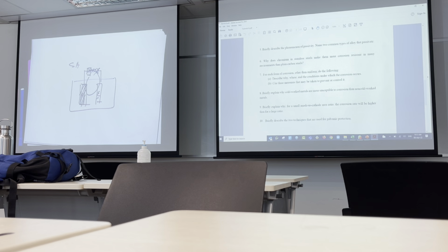Okay, so the two methods: sacrificial anode and impressed current. With impressed current, you do not have a consumable anode that has to be replaced. You use something that's inert. Inert means it just becomes an electrode to fulfill the requirement of the electrical circuit. The electromotive force that drives the current comes through power generation, basically a device to pump current inside.